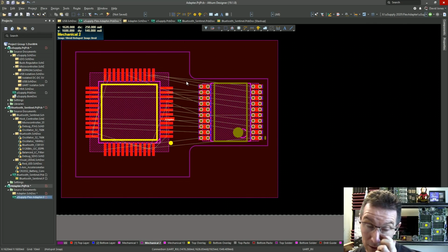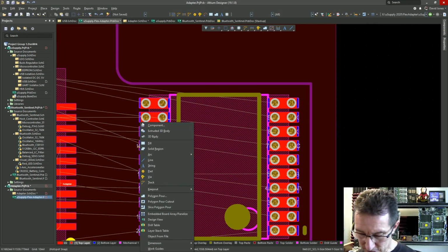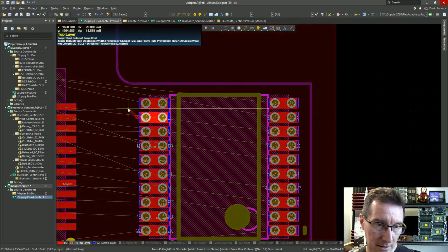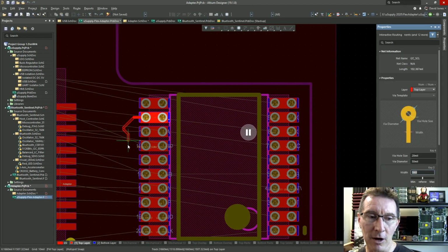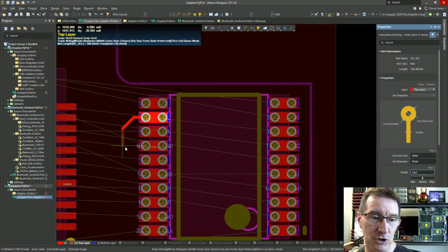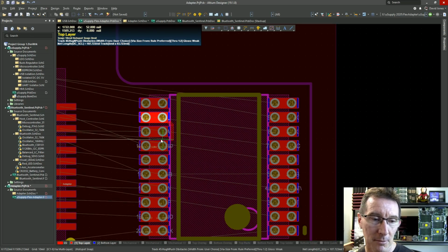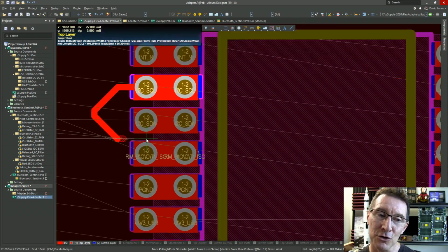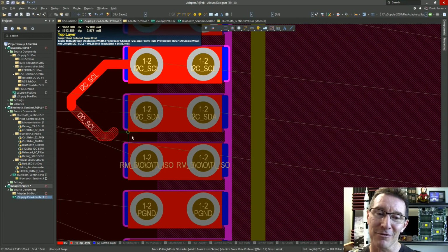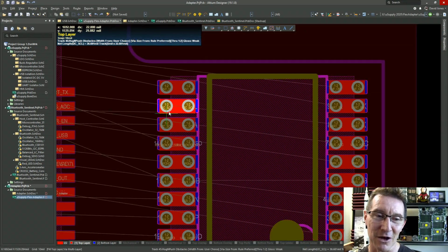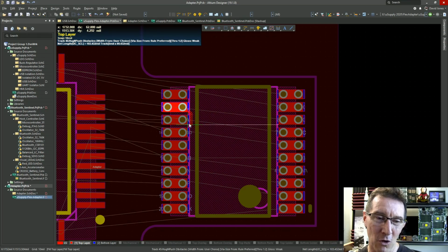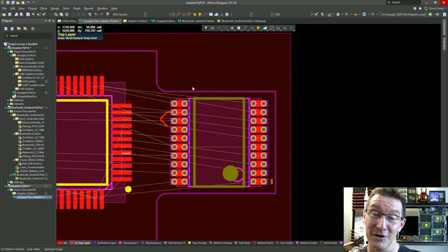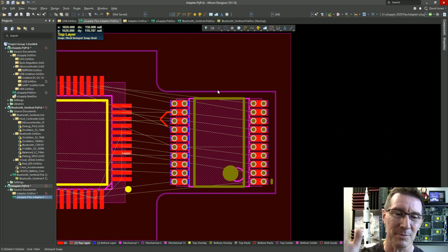Right, so let's actually just place a trace here. Just willy-nilly, right? This is a 5 thou trace. You don't want to go much smaller, but are you going to be able to get that through that pad? No, you're not. See, that's the problem, right? We're constrained. So really, we've probably got no option, unless you want to go to really fine tolerances. Why? Because you're just going to pay more.